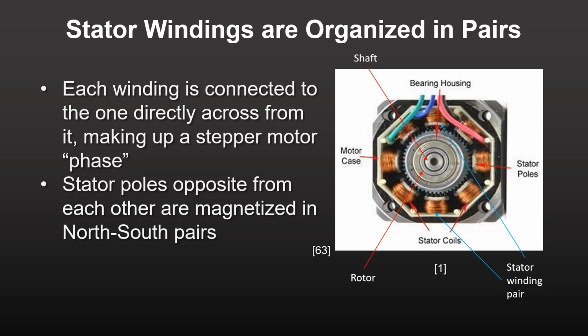This design is called a hybrid stepper motor, featuring step angles as low as 0.75 degrees. The two rotors are made of permanent magnets, one polarized north and the other south. Numerous small teeth exist on the outer perimeter of each rotor, as well as on the inside perimeter of the stator.